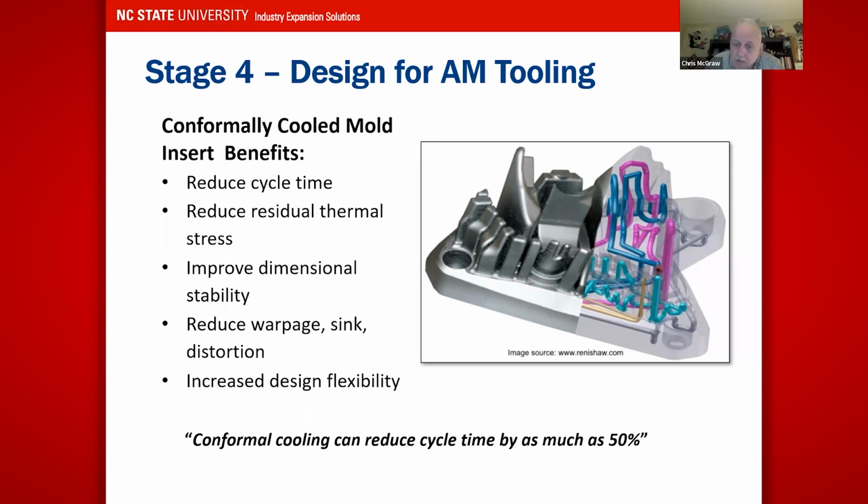If you just look at the drawing there, the picture, if you just follow the purplish color tube, that's getting coolant to the proper area where it needs to go. We could not ever make this with traditional manufacturing, but with additive, I can make all sorts of channels and ways to get things into where they need to be internally that I could have never done in the past. So that helps me with my dimensions. I have all sorts of flexibility in ways to make things. It makes my designer's job easier because he or she can make what they need to make. And you see the statement at the bottom that this cooling can reduce cycle time by as much as 50% by cooling the part and keeping it the way they need it.